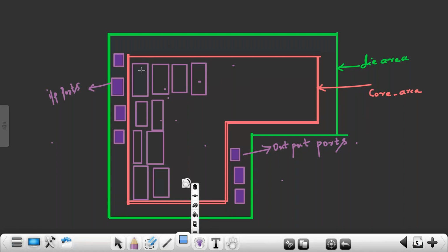For 20 macros or for 10 macros, I'll be having 10,000 cells extra in my design. For these 10,000 cells, I have to do PD. Instead of that, the macro is already done. This SRAM macro is already designed, and I will purchase it from the vendor. He tells me that his macro is best. I'll directly purchase from the vendor.